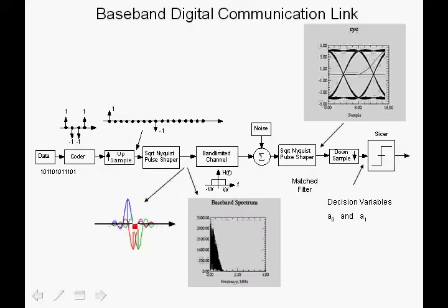Each impulse response is the symbol for a Nyquist raised cosine pulse, which, as we have indicated before, has 0 crossings at equal intervals. So at the sampling points shown here, we have 0 intersymbol interference from the pulses. That is a nice property of the raised cosine filters.